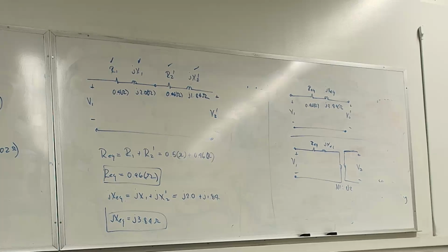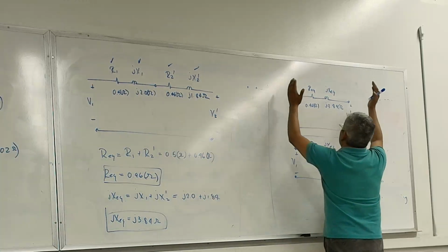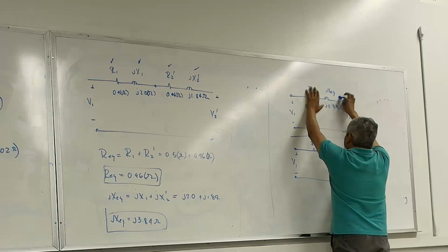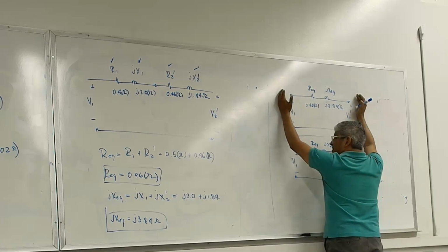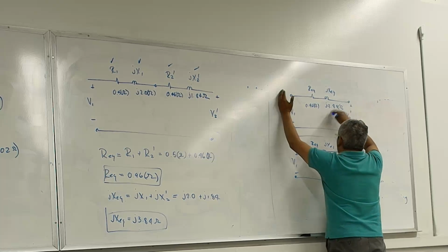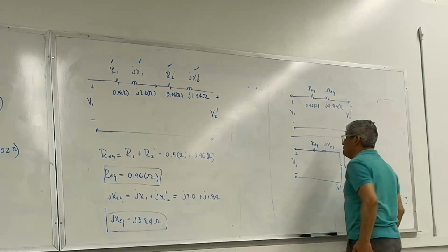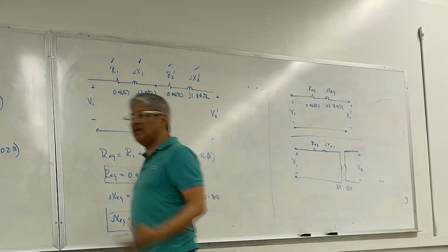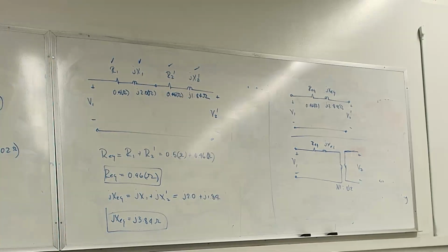I'm gonna say it again. I'm repeating myself. Somebody says, oh, by the way, they should give you this value. Sometimes they don't even give you that. Oh, here is the transformer impedance. And like I said, 95% of the time, they give you that impedance the same from the primary. And they just give you X equivalent and R equivalent.